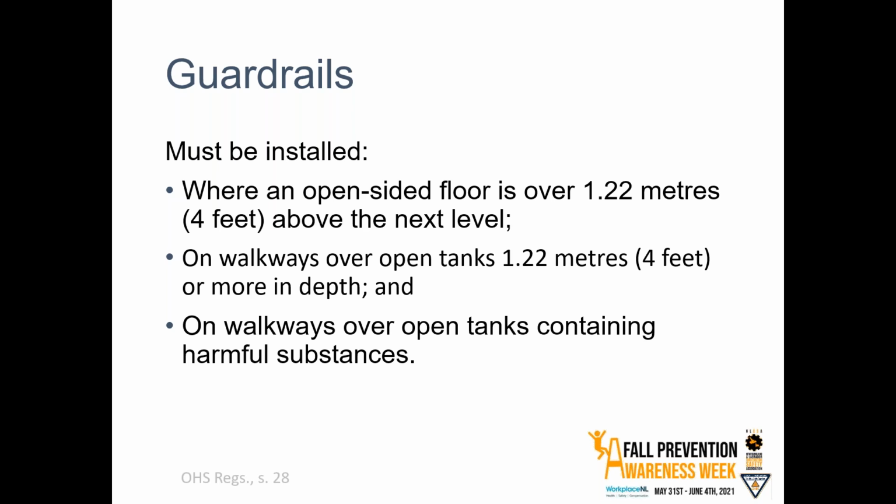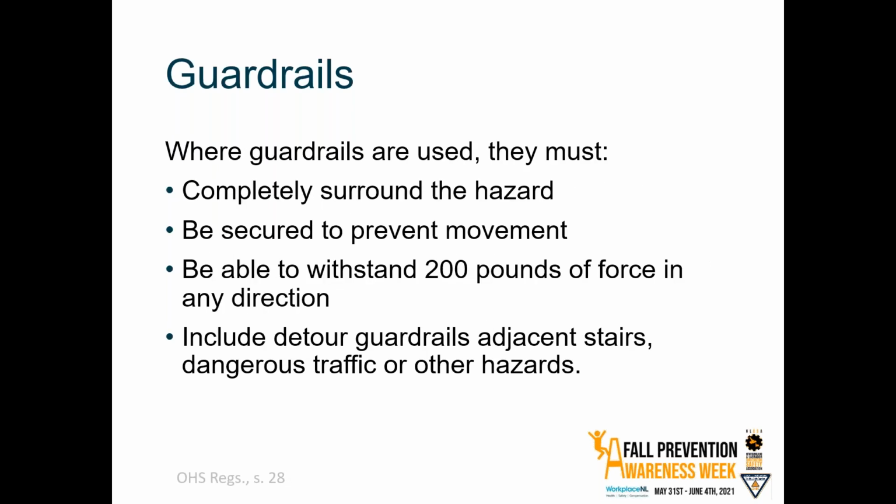So again, guardrails are a little bit different than the working at height legislation. It's the 4-foot instead of that 10-foot piece. Where they are used, they need to go all the way around the hazard. This is a really important one. I find a lot of the times on work sites, little gaps are left for equipment to come in and out, or for people to come in and out, but it is really important that that guardrail system goes all the way around the hazard.